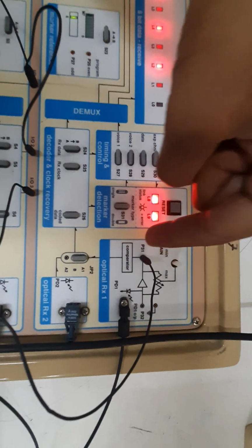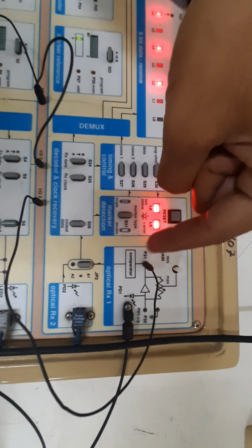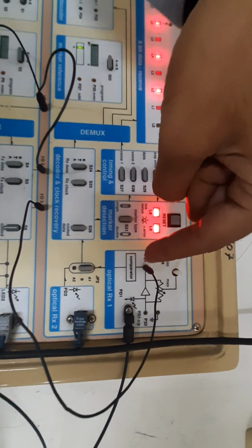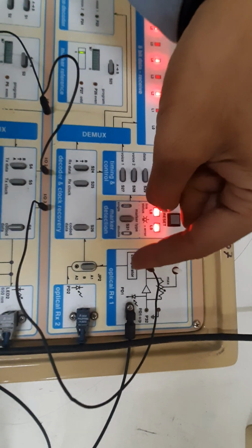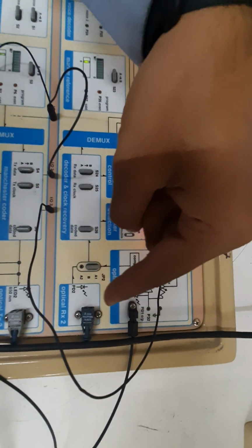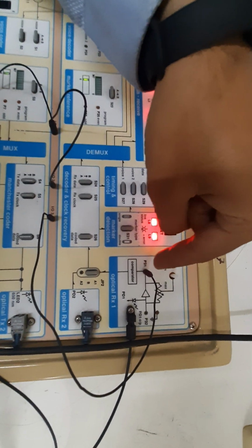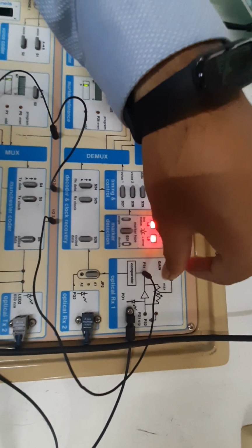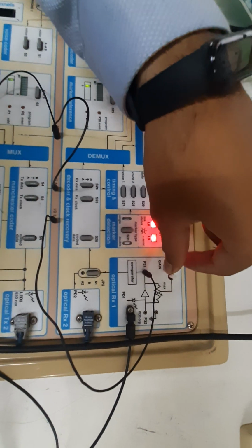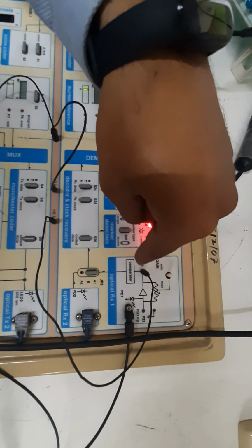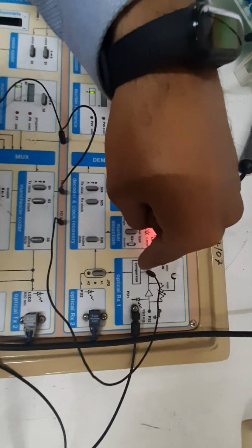So we'll be measuring that output at P31 because if the strength of the signal gets reduced, let's say after passing through that optical fiber, we can change the gain of that particular received signal also by adjusting this gain knob, which is kept here. So this is the P31 point. We'd like to measure the output at this point P31.